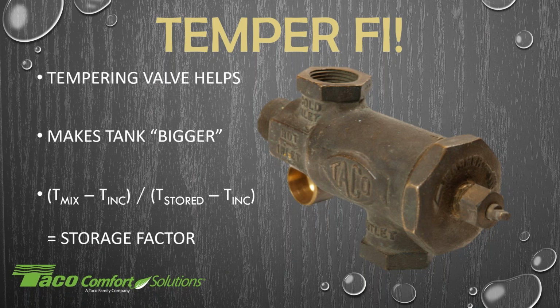And there is a formula available to do that. What you see here is a storage factor that we will apply to the usable capacity of a water heater to get more output from the tank itself. T mix is our mixed water temperature that we're sending out to the fixtures in the house, minus the temperature of the incoming water from the street or from your well.